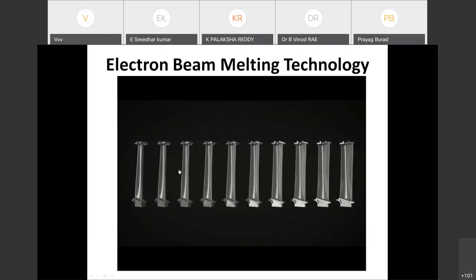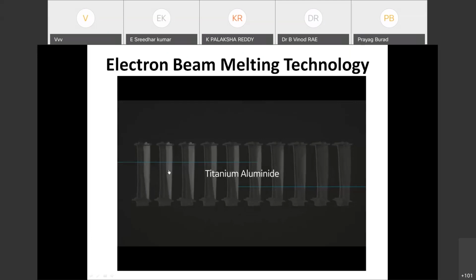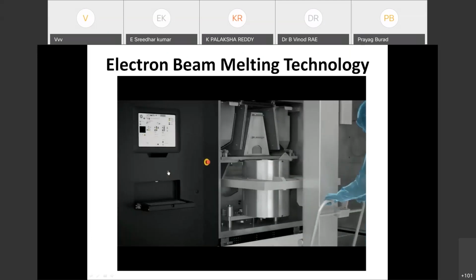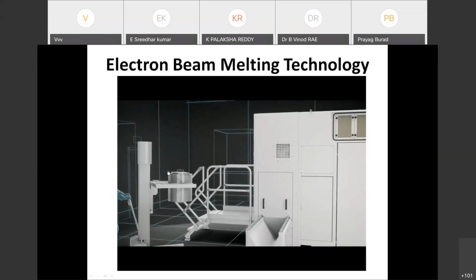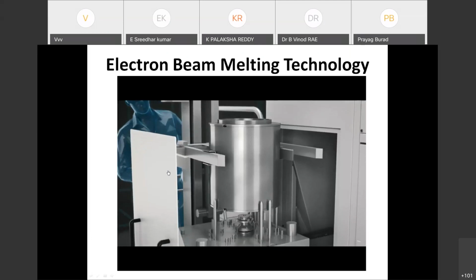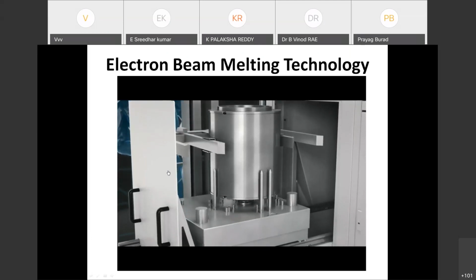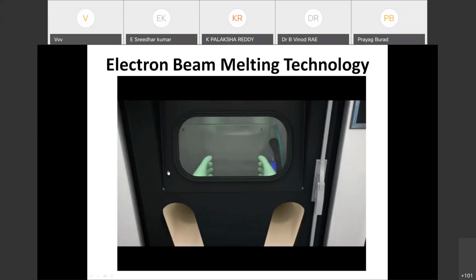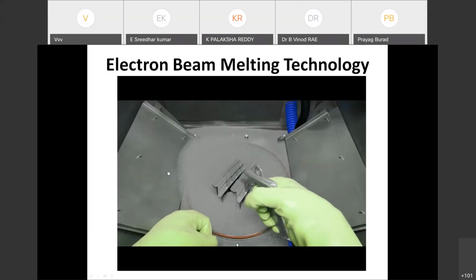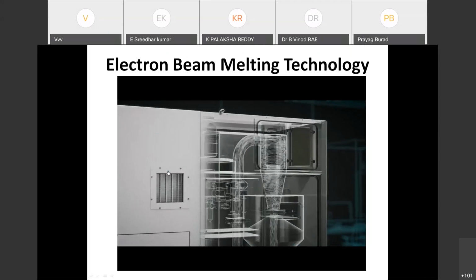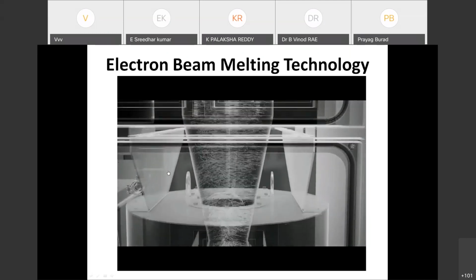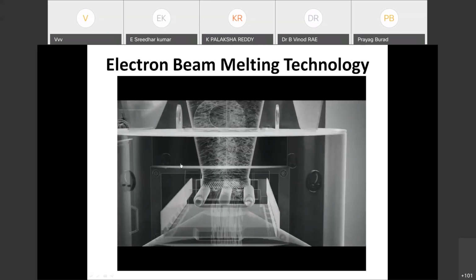GE's is titanium aluminide based. Removing the build from the machine and taking it to the recovery unit, where the uncured powder will be removed. You can see the uncured powder being removed, recycled and collected because the powder is quite expensive, and moreover it's harmful to human health.